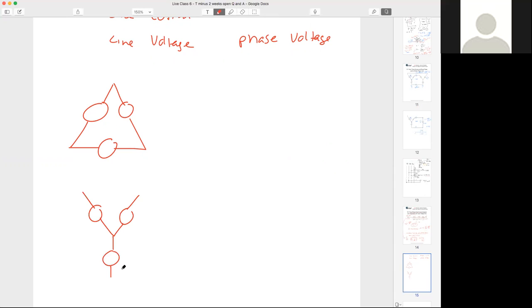No, be very careful, Shamil. When we give current values, they are always per phase. The only time that 3 multiplier comes in is power. Your total 3-phase power is the total power in the system. Line current is the individual line current per phase, and it's always going to be equal for a balanced system. So be very careful. That'll get you in trouble.